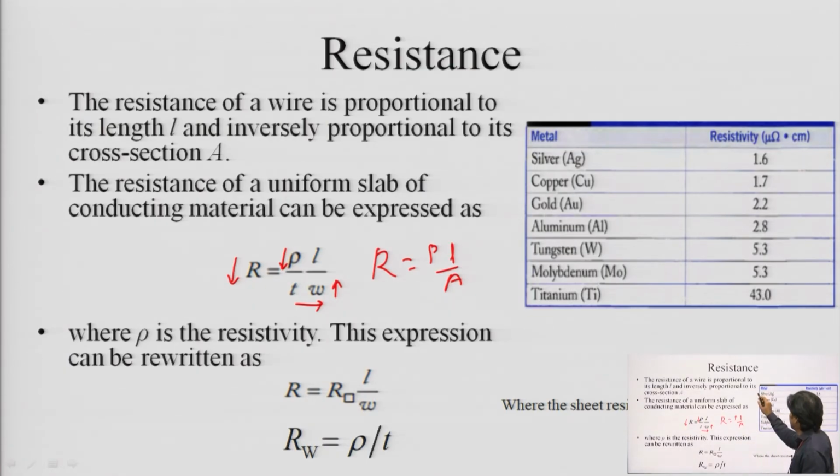Clear? So, these are the different materials that can be used for interconnect application, but that depends on what particular technology you are using. Earlier we were using silver and aluminum, and gold also we have used, but it is a very rare material, so we are not preferring it. Apart from that, we are currently using copper because of its availability and better immunity than other materials like aluminum and silver. It has better electromigration immunity, and the resistivity is also lower compared to aluminum.